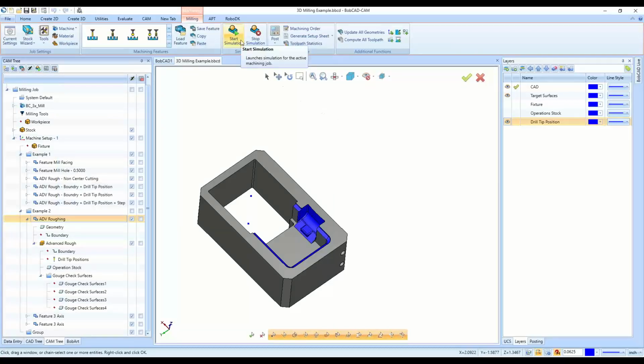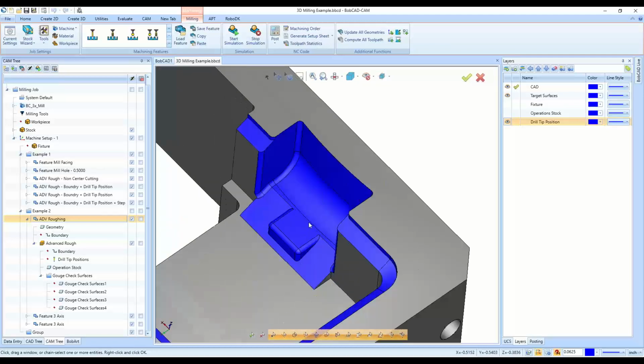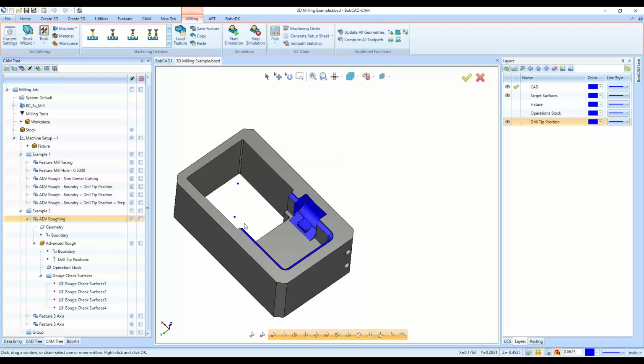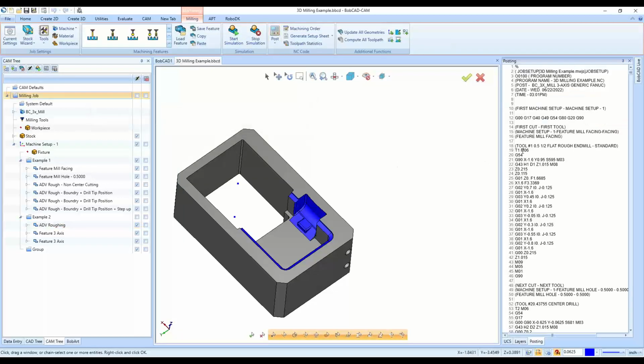And that was the toolpath that was focusing just on that area, working to pocket down into these 3D surfaces and all the way around here as well, instead of doing any air cutting and doing anything like that inside the pocket that we've already milled. Now that's about it. After the simulation, again, just post the G-code. It'll generate the G-code here, save, send it to the flash drive, and go from there.